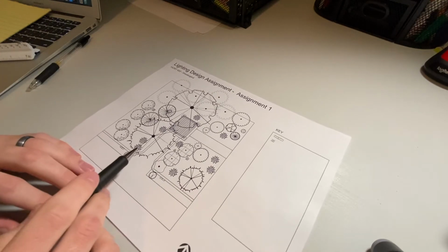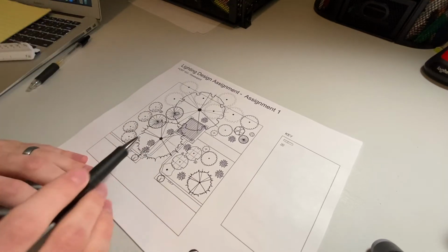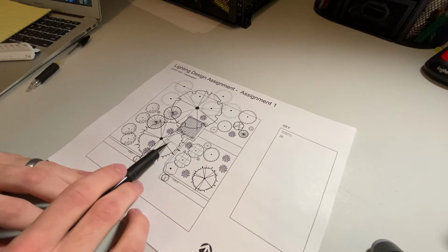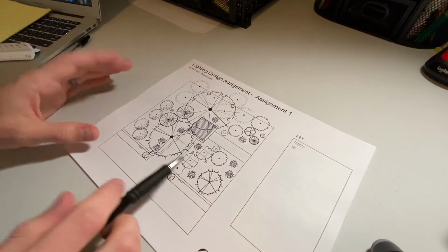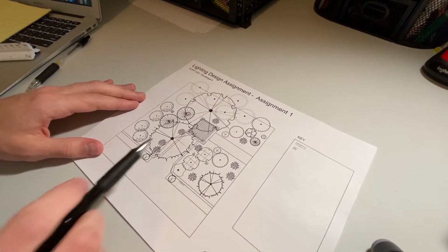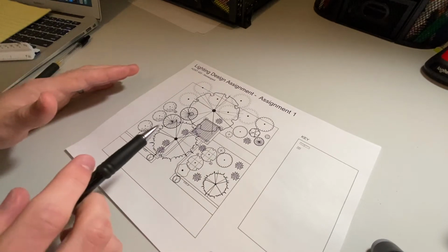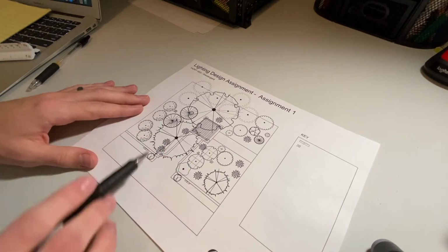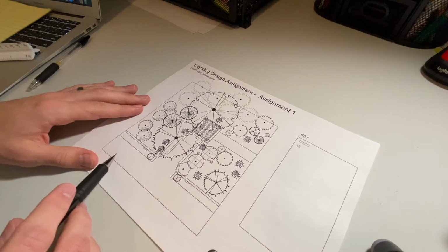And something else to remember when placing lights is where the transformer is, okay? Because you don't want to be placing lights everywhere and then be like, okay, how am I going to wire it? So you can see this line here through the sidewalk. There's a pipe underneath the sidewalk where we'll run line. And so we can't go under the sidewalk anywhere else. It's only right here. So keeping that in mind, we have to make sure that we plan accordingly. And so these 3 lights will be running under here to the transformer, whereas the rest of these will just run back to the transformer a different way.